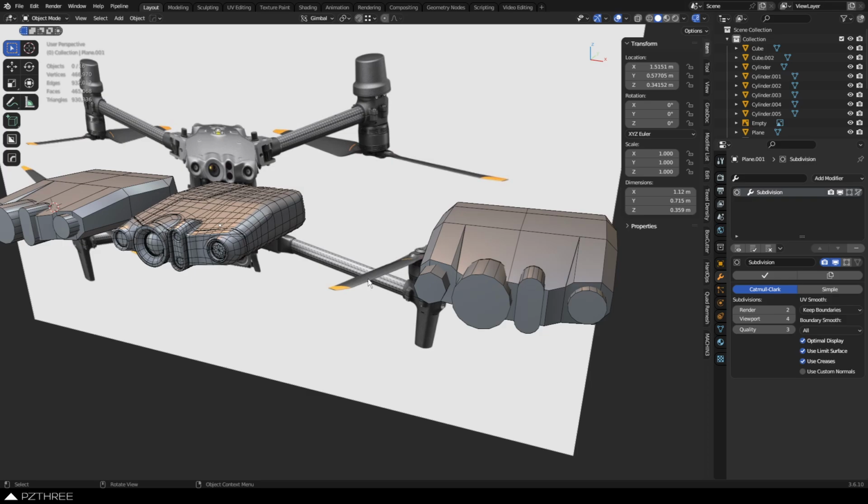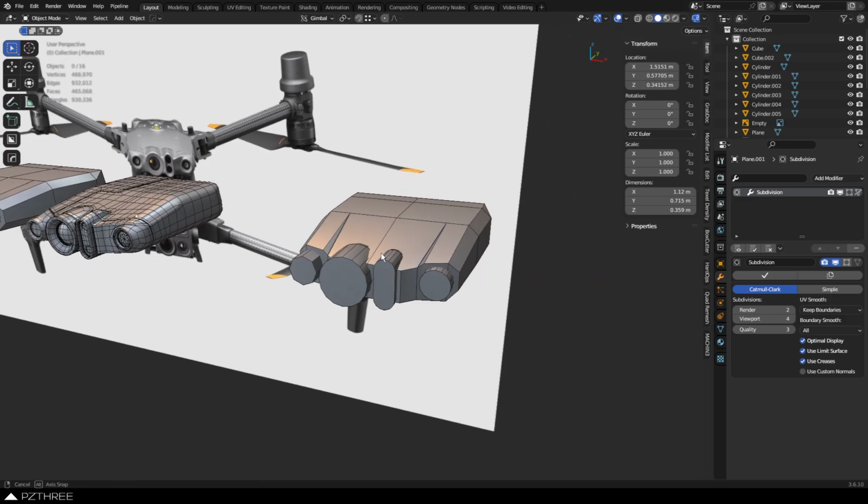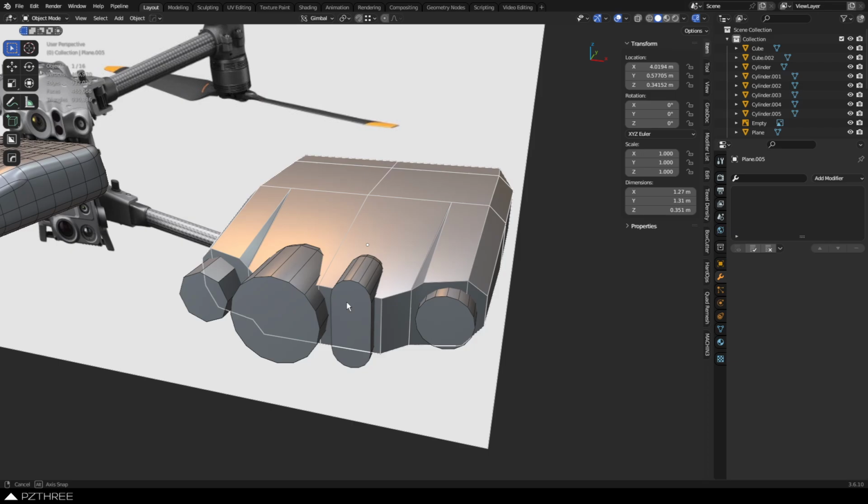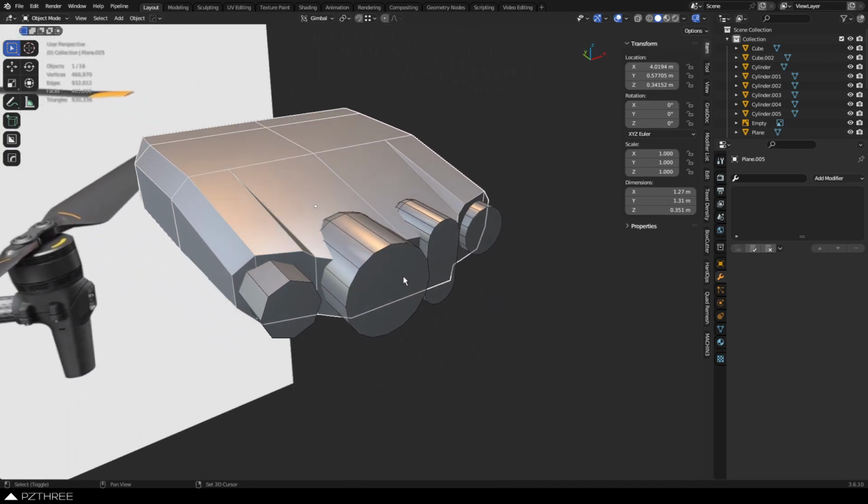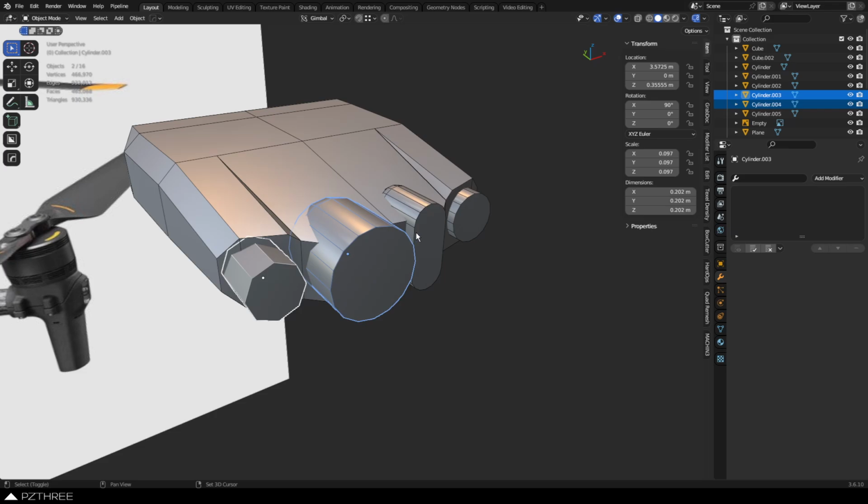But there's also, trying to think of the name here, rotocasted, where it's like a hollow shell inside or a hollow mold, and they spin it with resin, and that way it casts onto the walls. So rotocasted is another type of mold to keep in mind. You want to look these things up, but you don't have to master them and fully understand them. But the basic ideas there still can play a role, because things might be CNC machined out. They might be casted in a mold. They might be screwed together later on or welded.